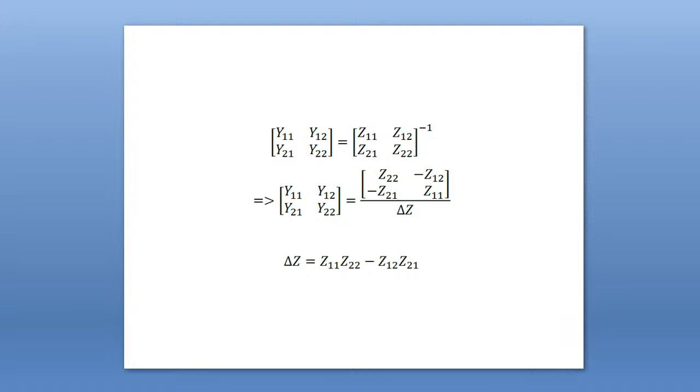You just use the relationship between z parameters and h parameter, and z parameter and ABCD parameter. First you consider the relationship, then you put in the values of the individual z parameters, and you check yourself for each parameter case: h11, h12, h21, h22.